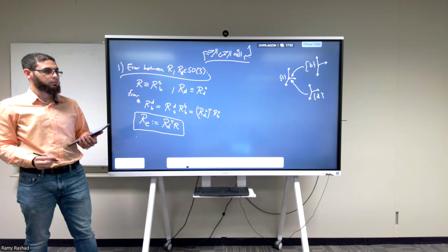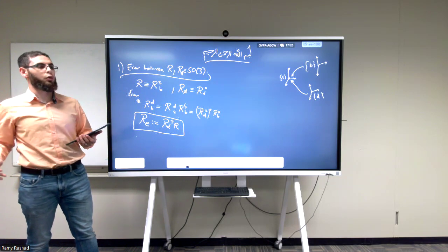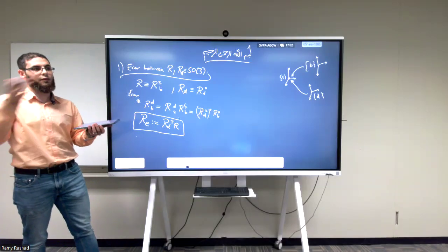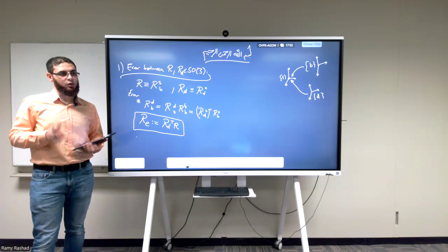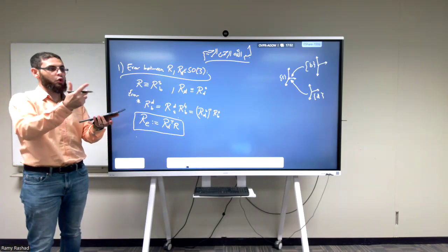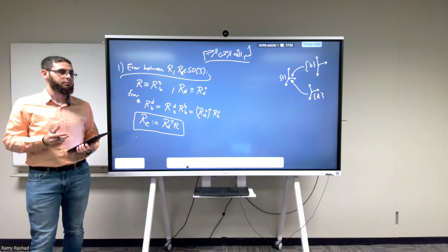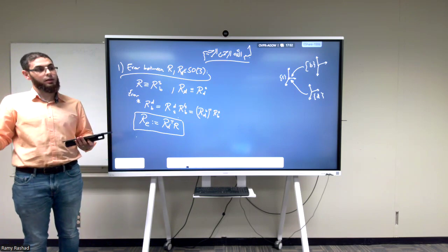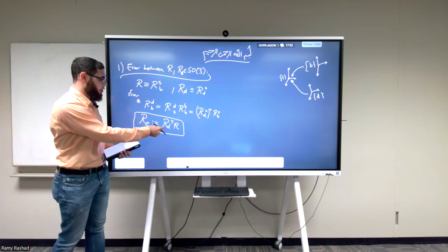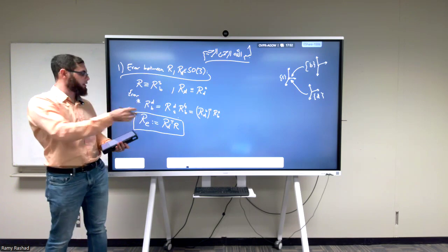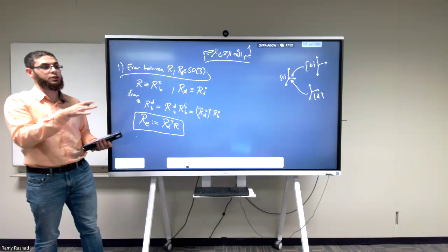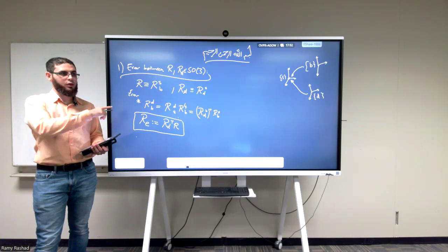There is a difference between taking B related to D and D related to B. The control law will look different, and you should expect that you're going to have just one rotation of the other in the end. They're equivalent, because they're just the same torque expressed in different frames. The torque will be the same, but if you write it in terms of R_B with respect to D, and I want to rewrite it as something with D with respect to R or B, this will just change. And also the meaning of the gains will change. This is also another thing. Okay, we're going to be doing it this way.